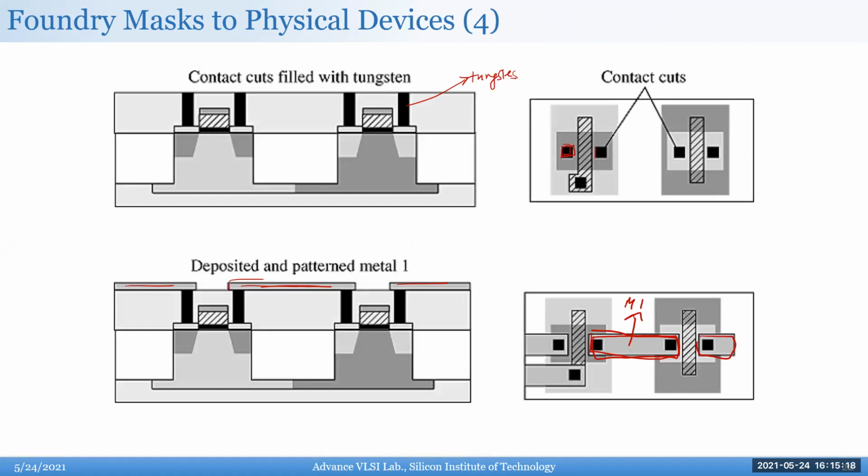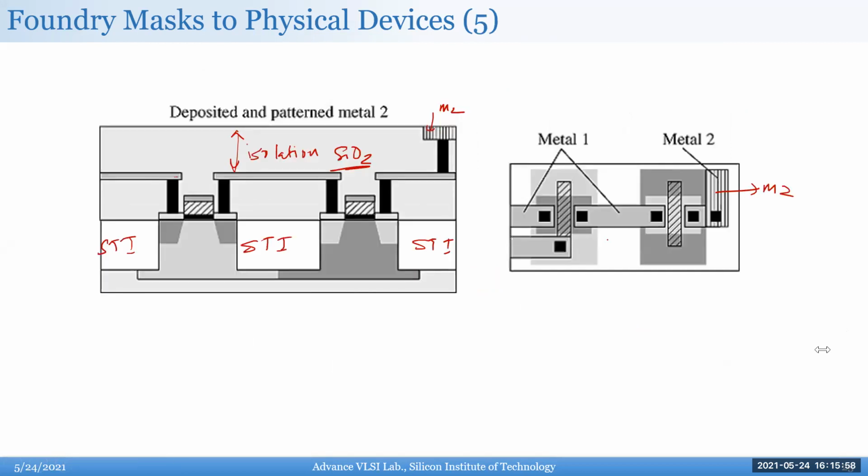So let me take it back here. The metal actually overlaps, right? So if I draw the 3D here, that's your 3D. The metal is overlapping this contact area. So if you do the metal first and then try to do the via, no amount of photoresist or anything will help you, because even if you make a hole through this, then you have to do a tungsten all the way here. Then you will have all sorts of problems of alignment, right? I mean, it is physically possible. I'm not saying it's physically not possible, but you're just going to do a tungsten all throughout, and you're not going to get the alignment which you're going to get with this step, right?